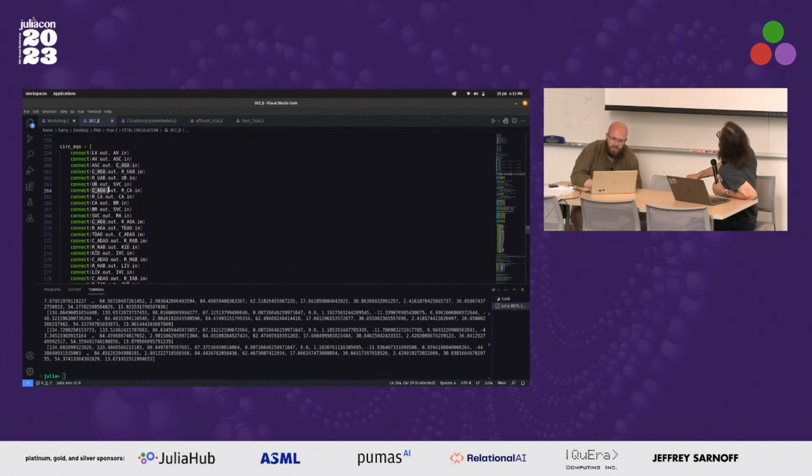So, yeah. There is at this stage maybe important to mention you can connect as many elements as you want with one connect statement. And that's how you had to do it in the early days of Modeling Toolkit. Now, Modeling Toolkit is really clever enough to just figure it out. If you connect element A and element B, and then in the next line connect element B and element C, it will figure out that that's a triple connection. So when you extend your network, you can now basically do it completely naively, just, okay, I want to connect this to this, and the Modeling Toolkit framework will figure out if that actually connects to 5 other elements or not.